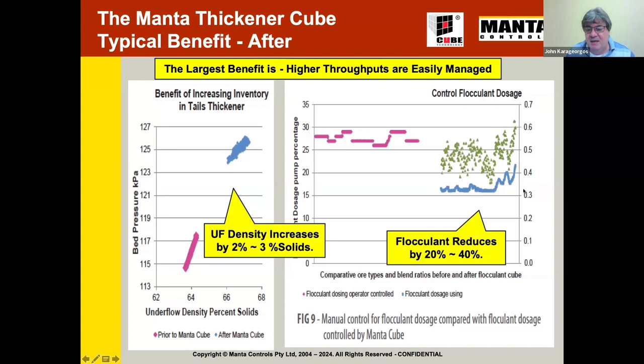We'll talk about how you know how much floc to add, and what really drives the percent solids. That's what we're chasing, and we're doing this at maximum throughput. And this curve here actually shows you something. You'll see there's a curve in this, so you'll see that soon.